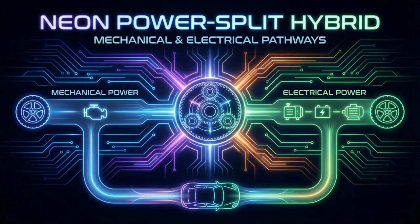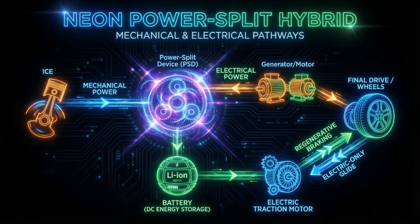The planetary gear set allows the engine's power to be split between the mechanical path, which connects power directly to the wheels, and the electrical path, which connects power to the generator, then to the battery, the motor, and the wheels. By varying that split, the vehicle can run like a series hybrid, a parallel hybrid, or any blend between them. Think of the PSD as a three-way junction that enforces a mechanical relationship between three shafts.